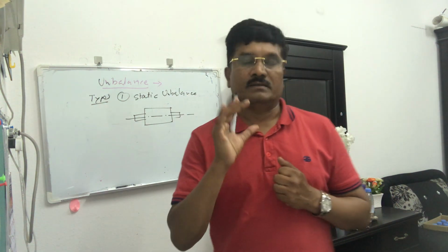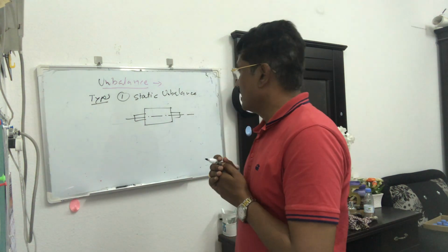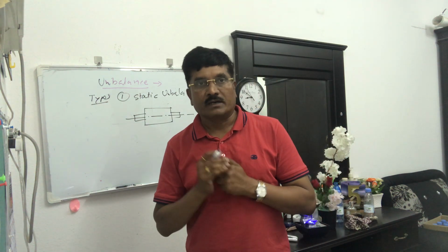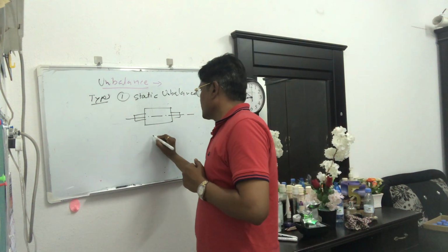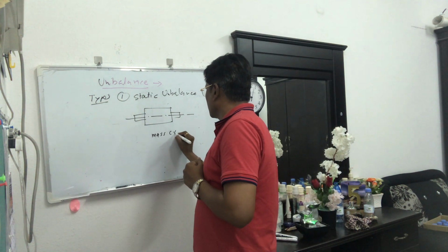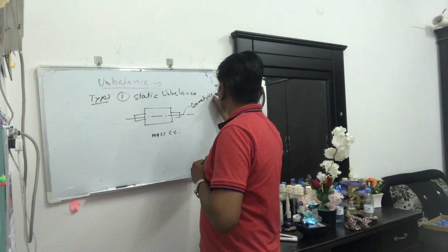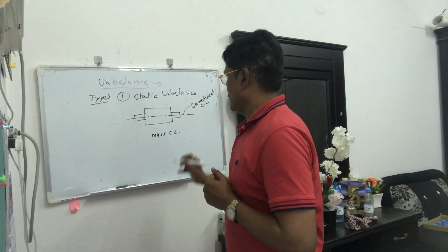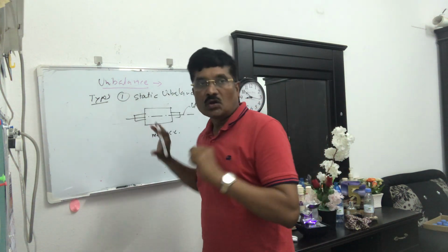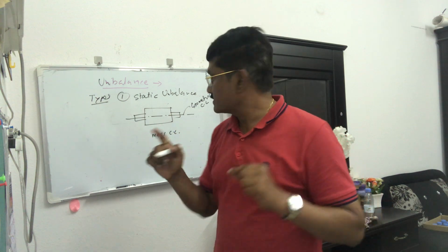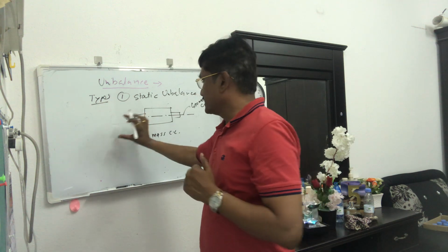And take a note that every rotary machine or every rotor has another center line. It is called as a mass center line, where all the weight is concentrated along that center line. And this is called as geometrical center line. These two center lines are different. Geometrical center line does not change its place, it's always there. It is prepared, or we can draw a center line by taking a dimension of the rotor, exactly half.